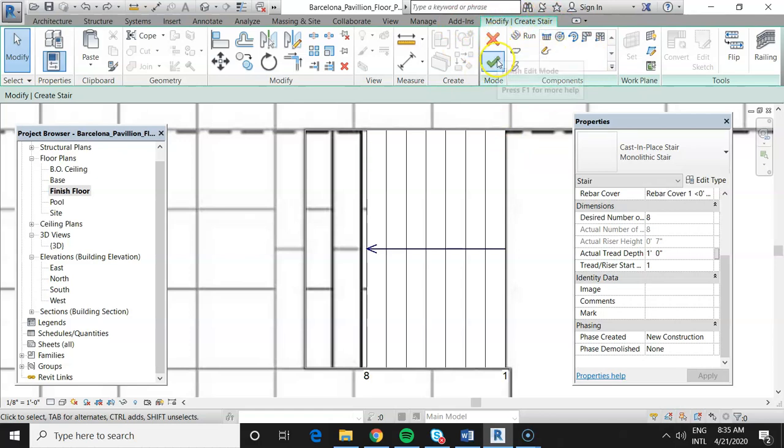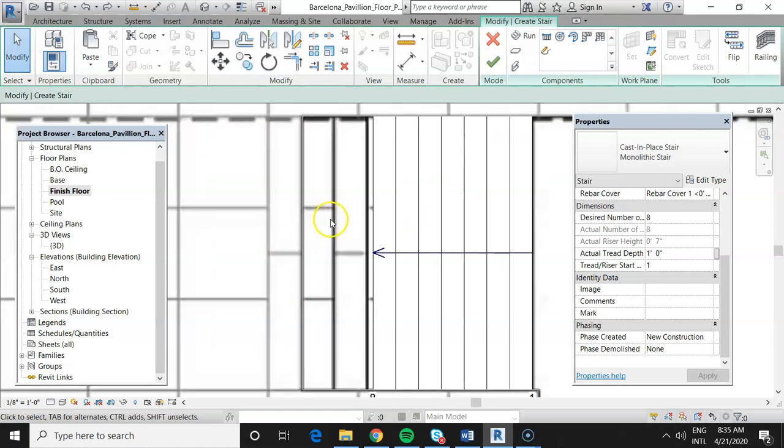That's what, again, when we see our red and green lights up here, that means that we can't do anything else. We are stuck in this until we either confirm or deny that we want this staircase. So I said that there was a lot of behind the scenes kind of things that we could adjust and that we weren't going to, but I lied because we will, so that we could deal with this hole. Looking at this drawing, assuming it's correct, the actual tread depth is a whole foot, which is generous. 11 is usually the magic number, but these treads obviously must be bigger. There's an entire 2 treads that have yet to be accounted for, so these might be 16 inches or so.